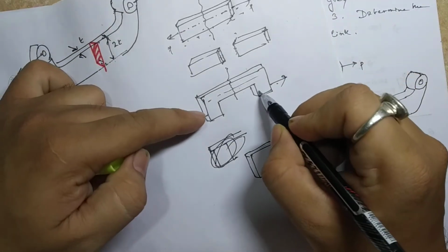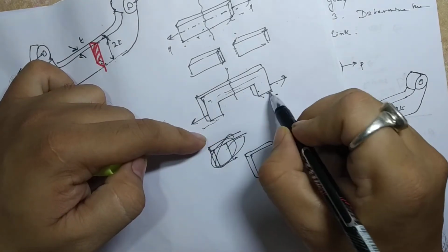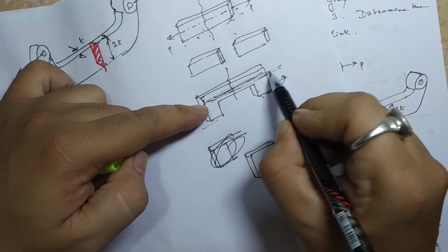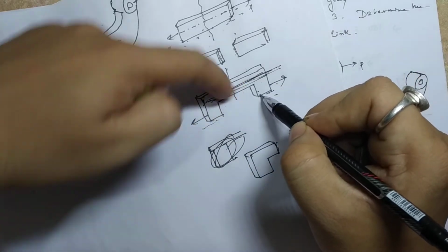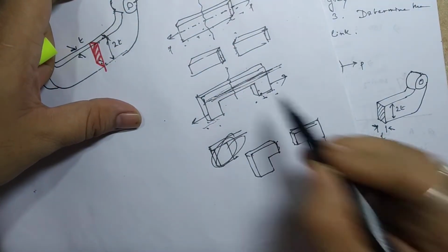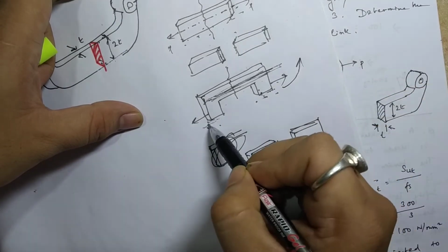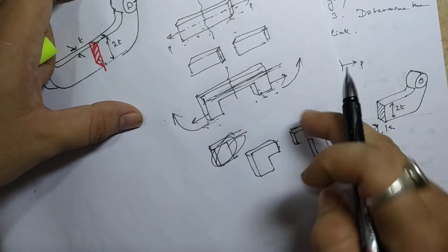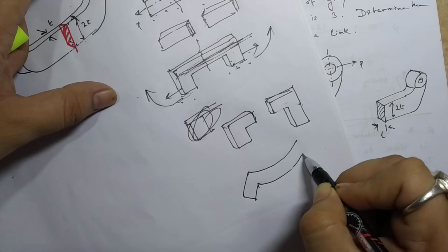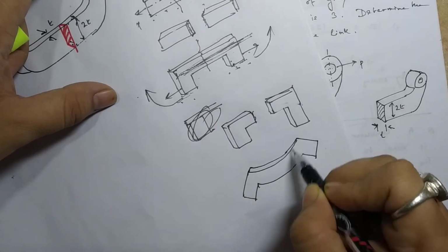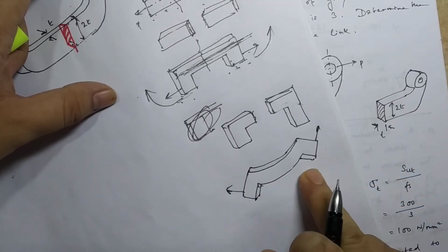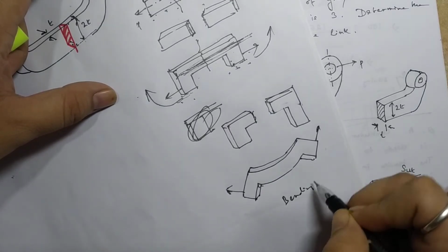Another possibility is that since the load is not applied along the axis, the connection is here, and we are applying a load away from the connection like this. It is obvious, just look at this figure, that it is going to bend the whole thing in this manner. If it is not breaking like this, then there is a possibility of bending the whole thing like this, isn't it? This is what you'll get, because they are pulling with the force. So this is the bending failure, and this is your tensile failure.